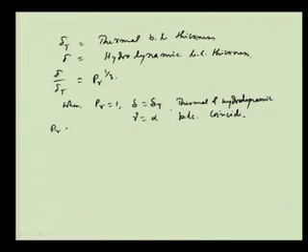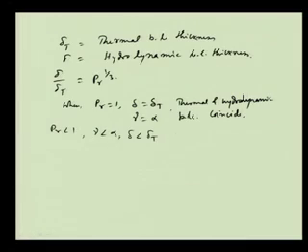This is when nu is equal to alpha, momentum diffusivity equal to thermal diffusivity. Then Prandtl less than 1 means nu less than alpha, and then delta is less than delta T. If the momentum diffusivity is less, then the momentum boundary layer thickness is also less.